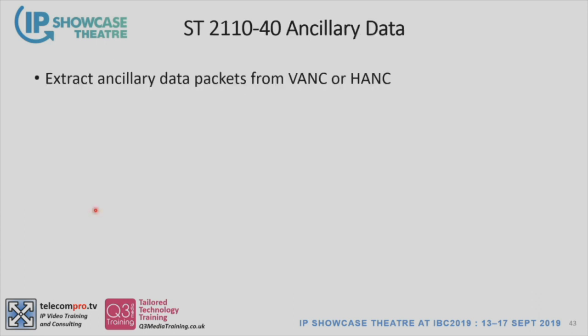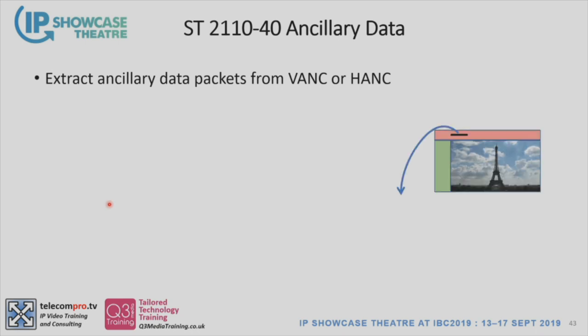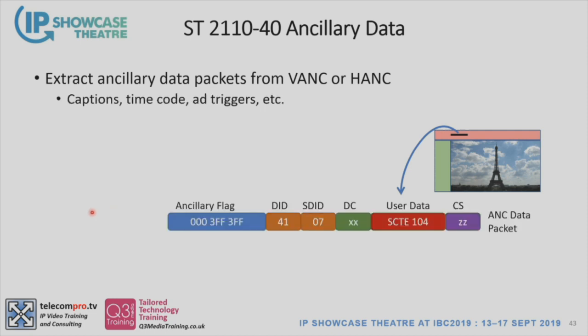So the next thing we want to do, and the last thing I want to talk about in this section, is 2110-40 ancillary data, all the good stuff that comes with video that needs to go over ST2110 as well. Well, the good news here is that that data is already formatted into packets. And you can see the packet format here. That's right out of the SMPTE standard, I believe it's 291.